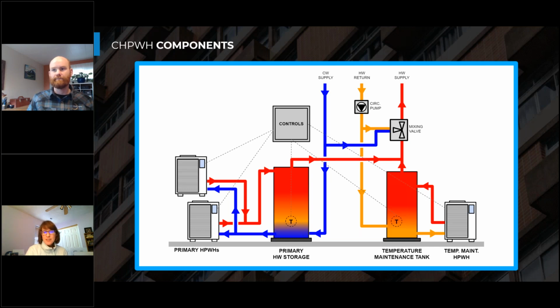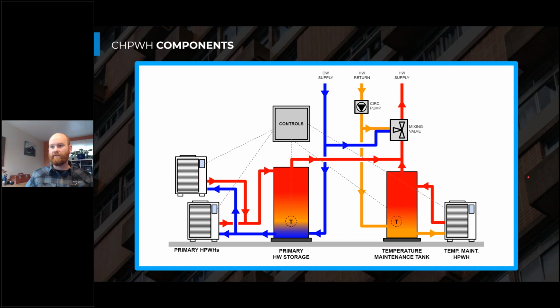Okay. Alan writes, do most commercial heat pump water heating systems contain multi-stage or single-stage compressors? Most of them are single-stage compressors. Because when we put compressors in series and have multiple stage compressors, we reduce the efficiency. Okay. All right. That's it for questions for now. Thanks, Colin. Great questions.